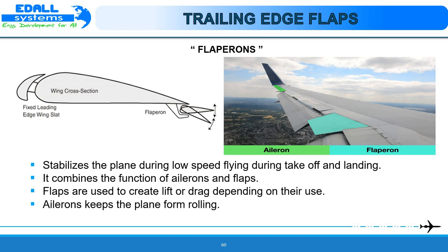The use of flaperons instead of separate flaps and ailerons can result in the overall reduction in the weight of the aircraft. Flaperons are often mounted well clear of the trailing edge of the wing to ensure undisturbed airflow across the flight control surfaces at low speed or at high angle of attack. This helps to reduce stall speed and improve low speed handling characteristics.